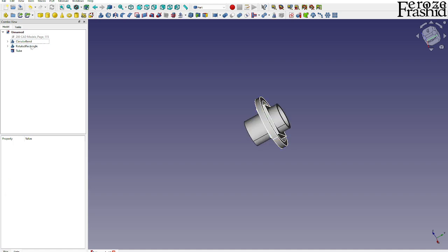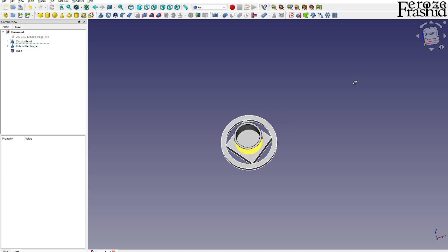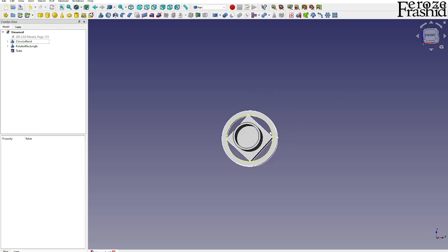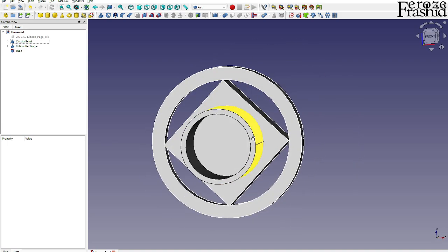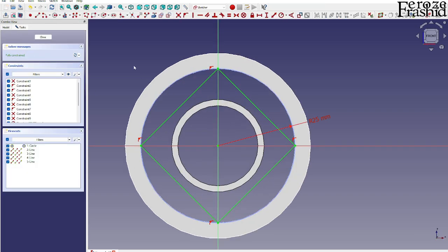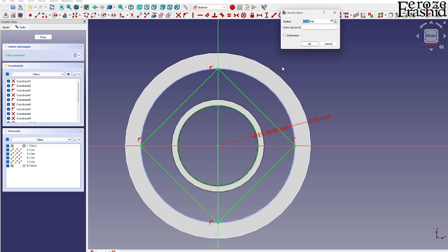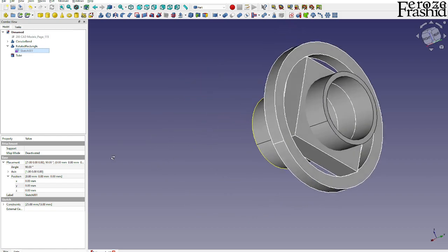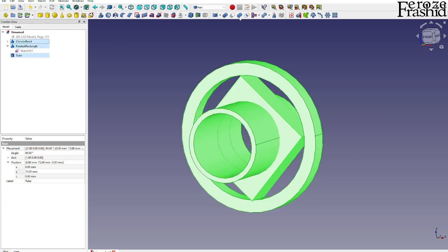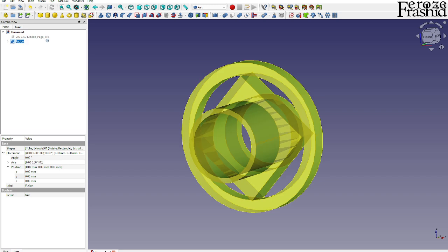I don't think this will work here. Alright, so on this one the connect tool would not work. We will have to delete this inside part manually. So let's go to the rotated rectangle and add a circular portion to it. And this one would be radius 13. Yep, that makes more sense. Now we can go ahead and make all of these one object, and that's our final object.